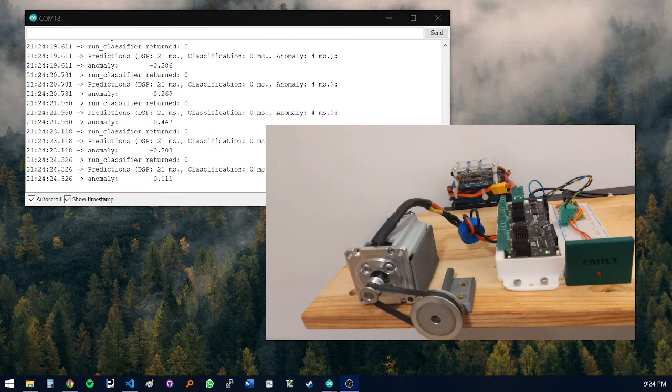So just to review, basically what we've done is we've trained a model using this kind of motion, and the model created clusters of expected behavior, or let's say average typical behavior of the motor, and it's constantly reading the current behavior of the motor and telling us when the motor's behaving in a way that is atypical. And so this is really useful and, like I said before, minimally intrusive. Very useful if you don't want to simulate faulty behavior, which can be very dangerous and damaging.